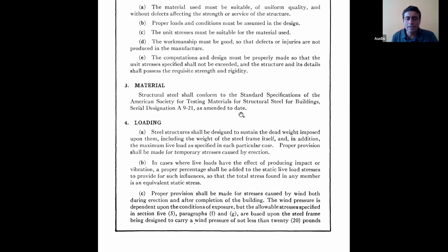Loading: the steel structure shall be designed to sustain the loads imposed, including the weight of the steel frame. Proper provision shall be made for temporary stresses caused by erection. Live loads, impact and vibration: you will have to add the impact of live load to the static live load. Proper provision shall be made for stresses caused by wind, both during erection and after completion of the building.